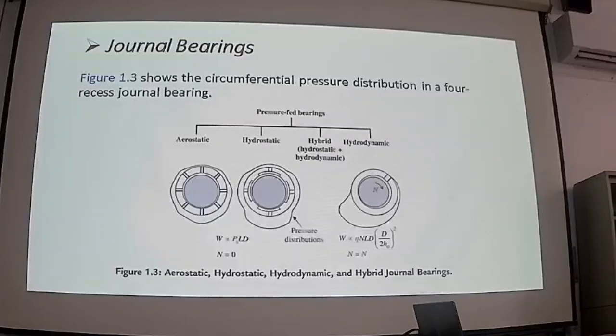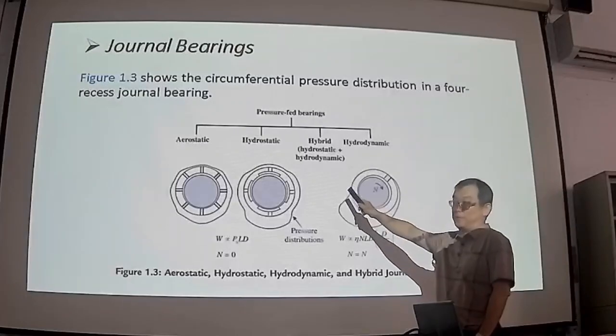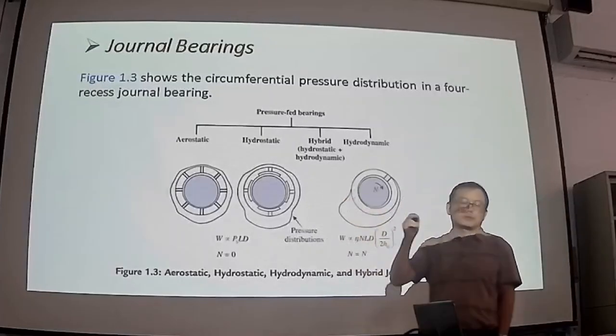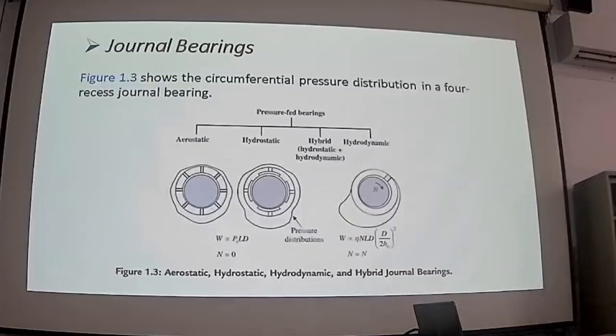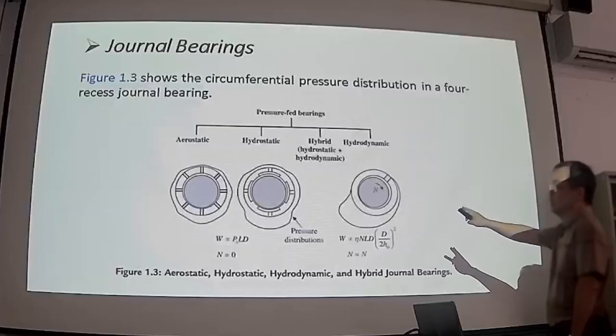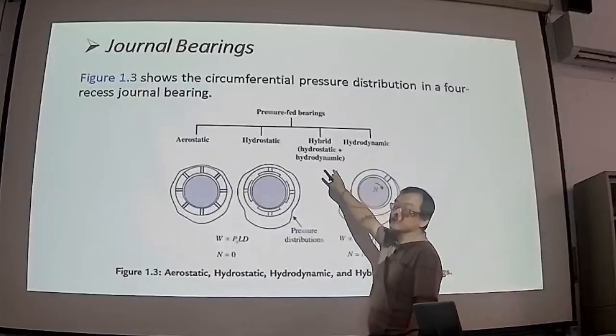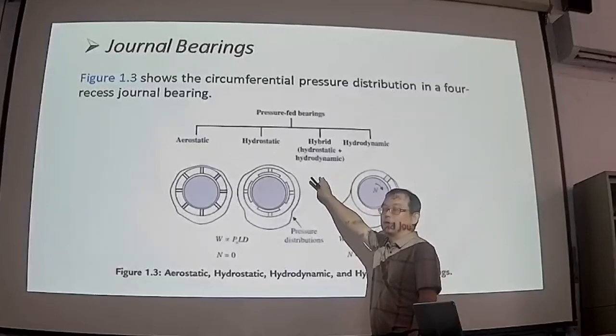From a theoretical point of view, we have made some estimations for that. For the rotational speed of the spindle, if it is smaller than 30,000 RPM, the influence is only 3 to 5%. We expect that if you have a rotational speed greater than 100,000 RPM, you will have a significant improvement in load capacity with a hybrid bearing design.